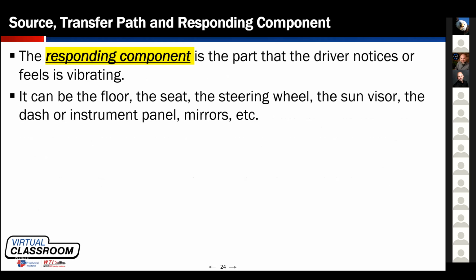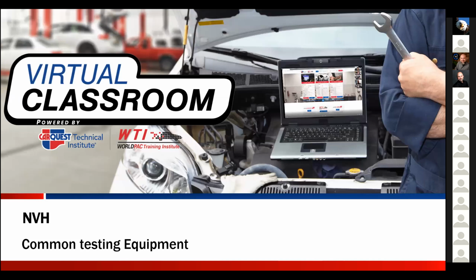Guys, the responding component is pretty basic. The responding component is what the customer feels. Look, when the customer feels a vibration, heck, when you feel the vibration or you hear the noise, it could be the floor, the seat, the steering wheel, the mirrors, the dash, the instrument cluster, you name it. It could be any of those. The responding component is what we're trying to keep the vibration from getting to. Okay, source, transfer path, responding component.